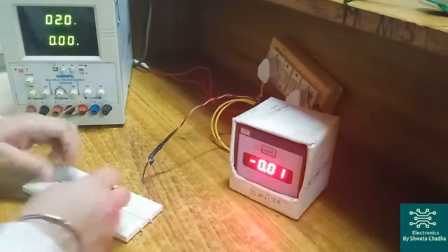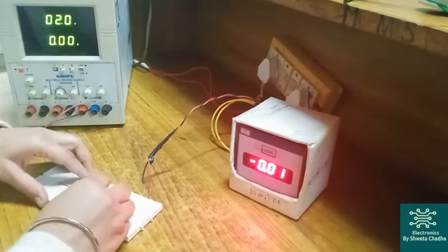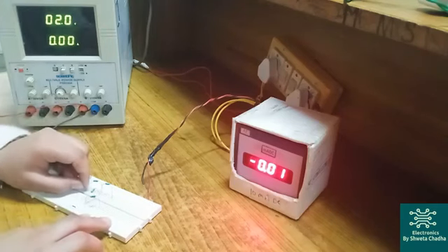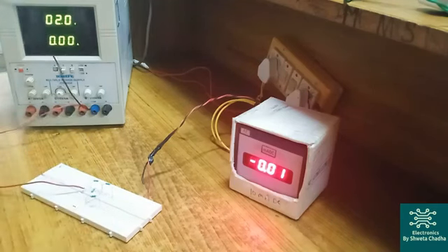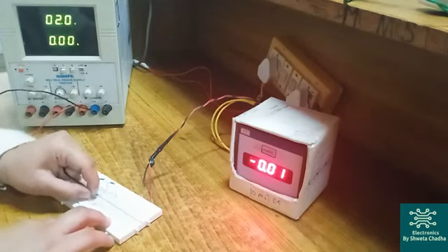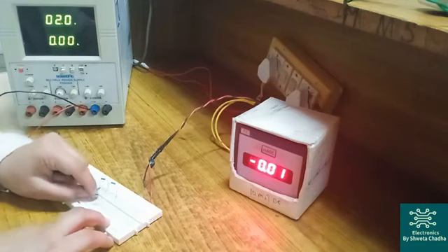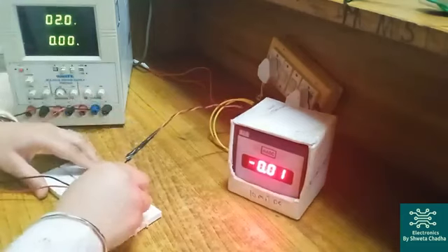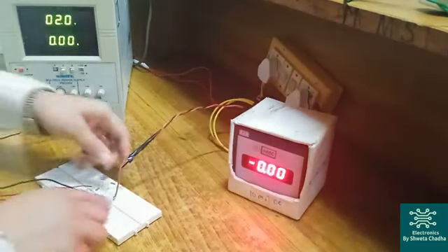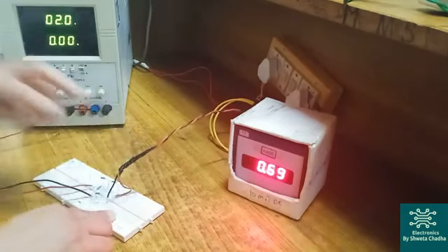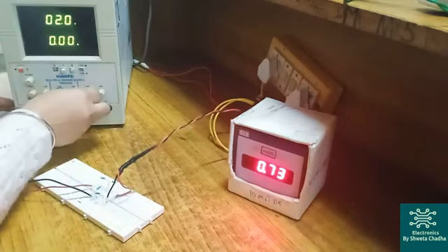RL 1 kilo ohm. The input supply positive with the first terminal of 220 ohm resistance, and the negative where RL and 220 ohm resistors are connected together. So again we have a column wise connection. And finally ammeter, the positive of ammeter with 220 ohm resistance like this, and the negative with RL. Let us set the input voltage to 5 volt.